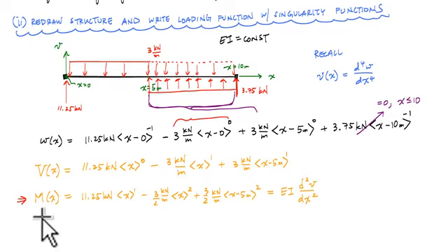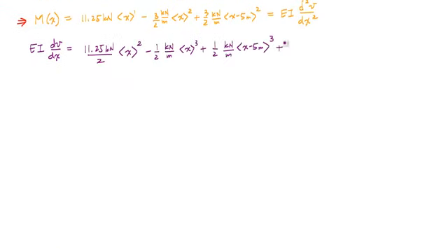So here, my slope description would be if I include this EI here. So this slope, integrating once, would be EI dv/dx, which is equal to the integral of this moment function, and that would just be, and here I have to add a constant of integration.